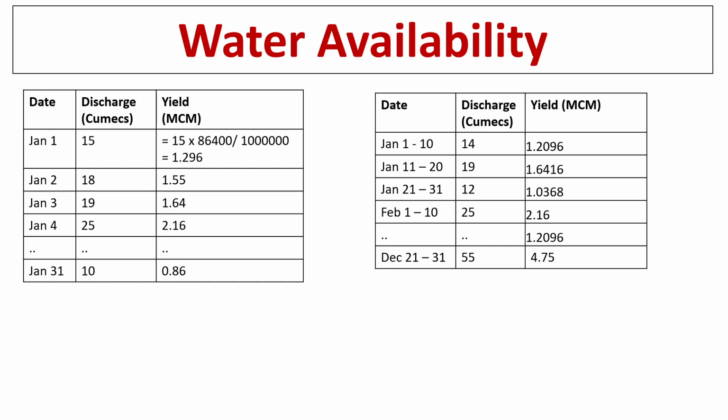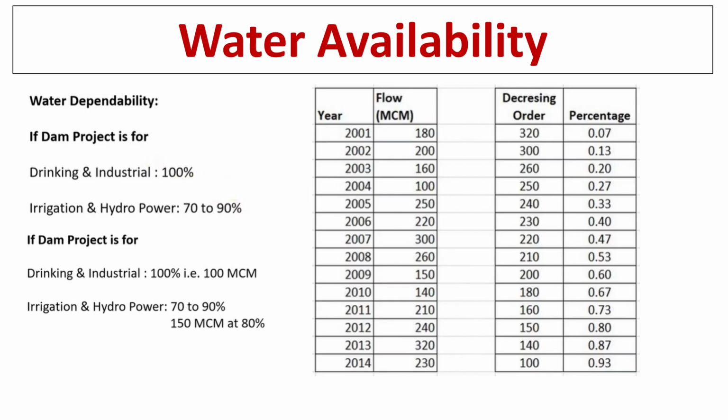Further, the same data can be converted to a 10 daily series. Because sometimes we have to do simulation for many years together. Using daily data and doing simulation will take time and it is required only in specific and accurate studies. For a broad idea of the simulation we can convert these daily data into a 10 daily series, which can be used in further analysis. We have seen the data collection. We will see how to process further.